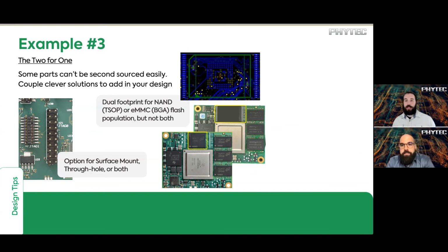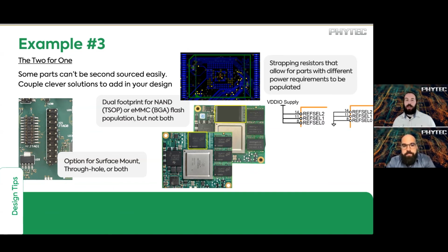Finally, when you're making designs, you want to add in design options that allow you to make decisions in the future that can allow you to populate multiple options. We know that space is always a constrained resource when it comes to PCB design, but sometimes making smart decisions can help you in the future. For instance, we have this USB transceiver here, where there are two parts that are available. One of them was supply constrained, one of them was not. And electrically, physically, and every other way, they matched, except for the strapping conditions on boot up in the mode that we wanted to use.